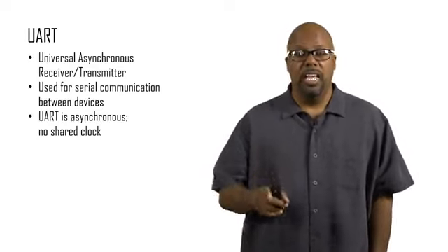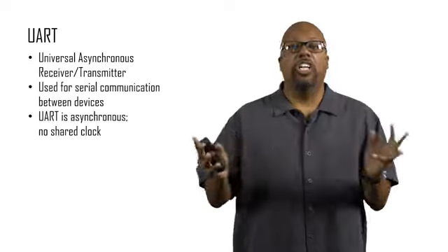Now, I don't remember the speed of light off the top of my head, but I know the clock rate of a typical processor. So let's take a processor, let's say 1 gigahertz clock rate, okay? Now, that's a slow clock rate for a modern processor or a desktop, but let's say 1 gigahertz. So if you have a 1 gigahertz clock rate, then you have a 1 nanosecond clock period. That means between 2 clock edges, you've got 1 nanosecond of time in between.